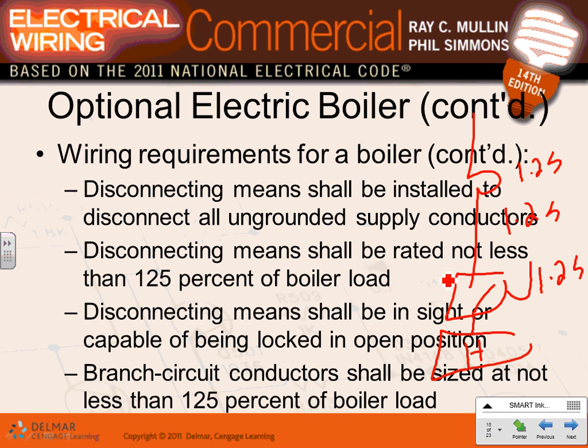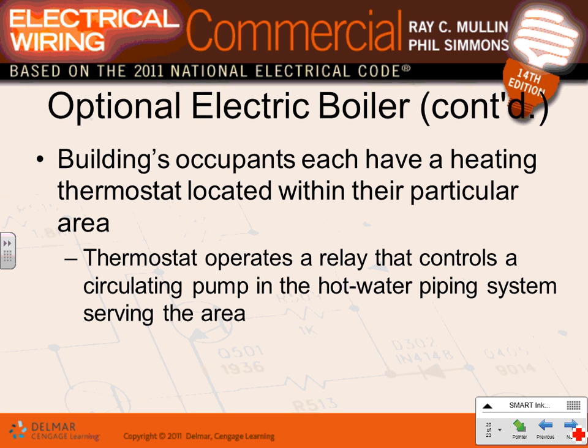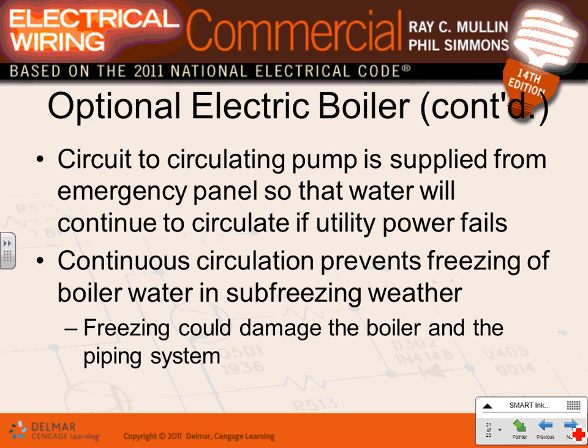Remember last project that we worked on heaters and we sized them? Nothing really new to comment about them. We talked about overcurrent device sizing for the electric heaters. We talked about the article that covers it. 424 is the article that tells you all the stuff that we did. Optional electric boilers, each have a heating thermostat. So inside the building, each will have a thermostat. The thermostat will kick in to get you the hot water.